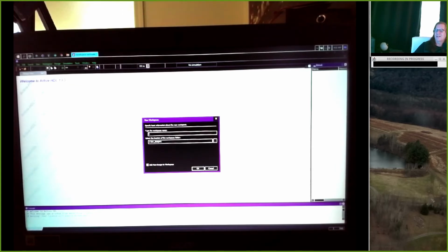If you're working on Lab 1 Experiment 1, make a workspace called L1E1 or Lab 1 Experiment 1 or something like that. Don't put more than one project in a workspace. It takes a little extra work to start a new workspace, but it is worth it, because if you start getting confused about which Verilog code is actually being simulated, you end up wasting a lot of time chasing specters.